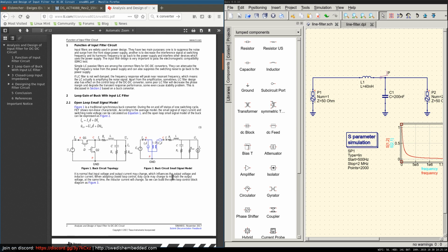And also, you cannot just reuse something that worked on a different circuit, because there are always different frequencies that you have to filter. So it seems to me there's no way around building the circuit for the first time, then testing it, measuring the emissions of that circuit, and then coming up with filter components. Because I cannot get all of the details just by looking at the data sheets. I can make a guess. I could design a filter that would handle the most likely frequencies that would be giving problems.